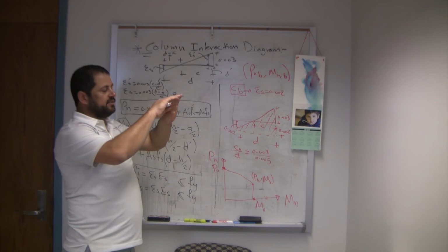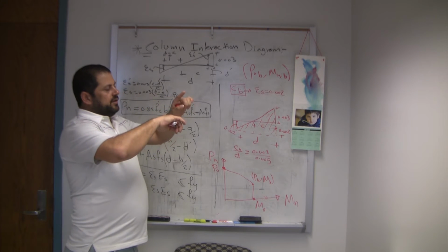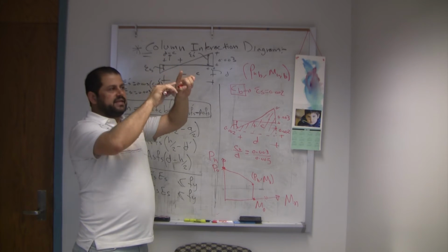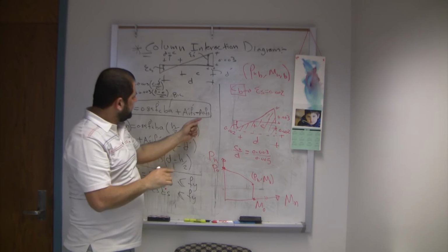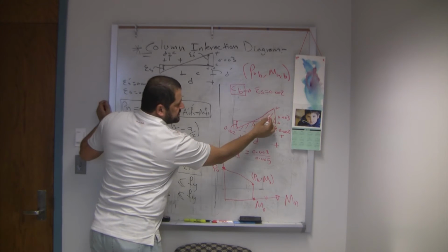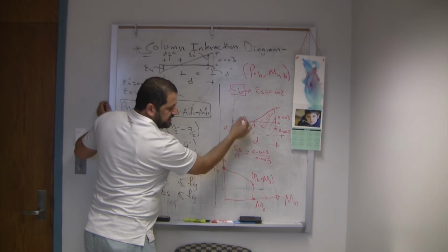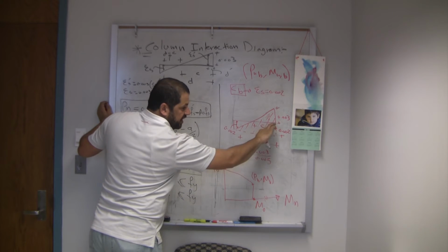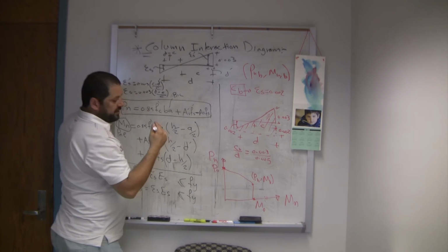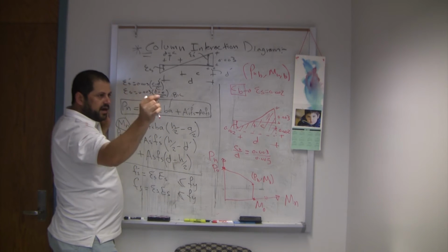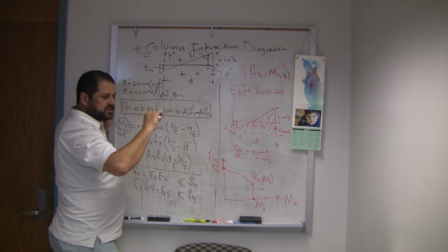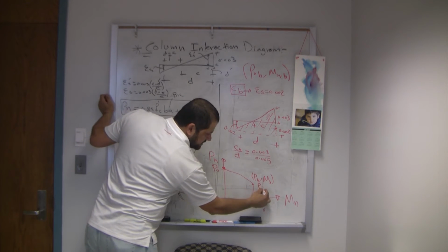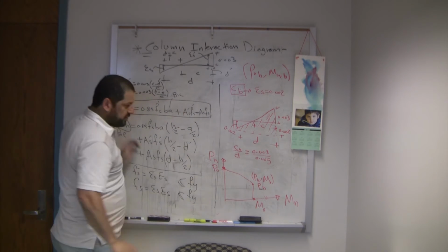Why? Because C is going up, it's shifting up. As the moment increases, C is shifting up. C is decreasing. It keeps going up. So this steel is in more and more strain. The strain increases here. So the neutral axis is shifting up. So again, if E is high, C is small. If C is high, E is small. So again, this one corresponds to E balance or C balance, but we'd like to have it with the eccentricity.